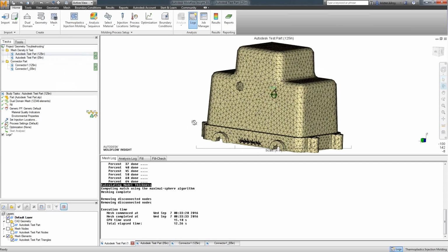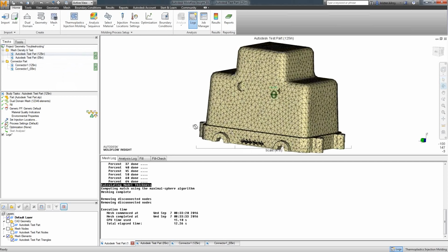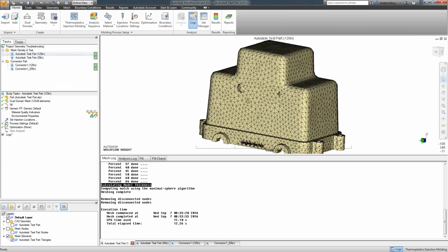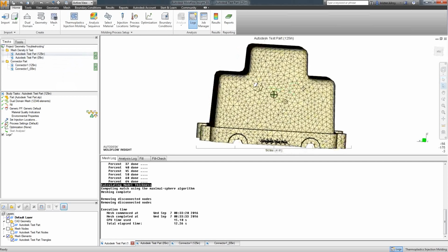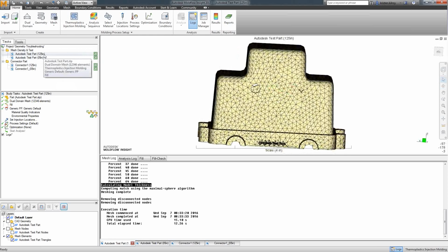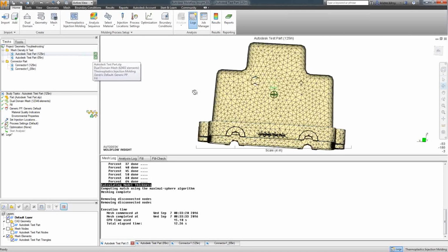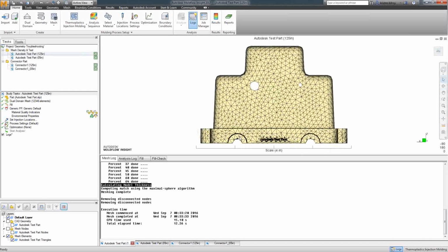And with this part, I just wanted to show you, again, the definition. With this mesh, I meshed it at an 1/8 of an inch edge length. You can see it's capturing the geometry. However, it is kind of clunky looking. It's choppy, whereas you're seeing really all those edges of the triangles in there.